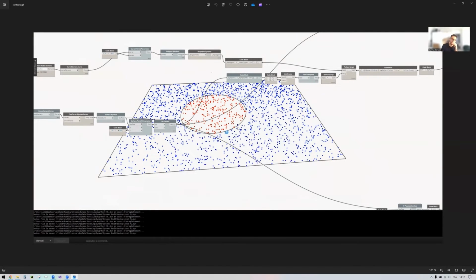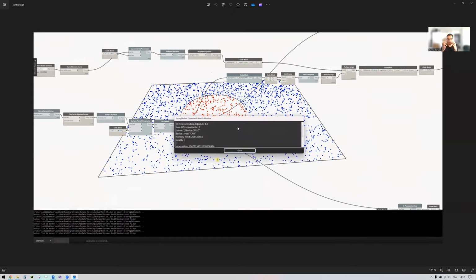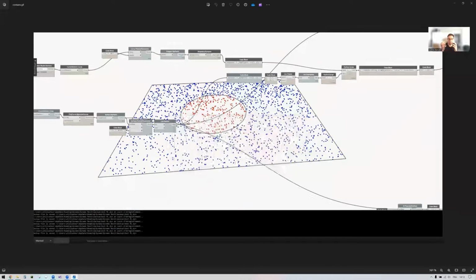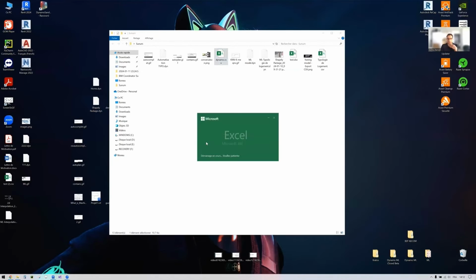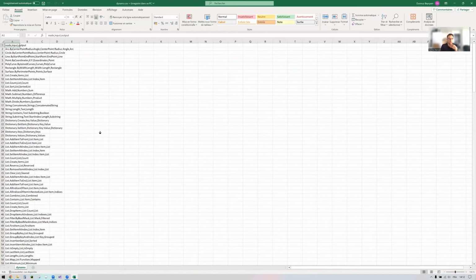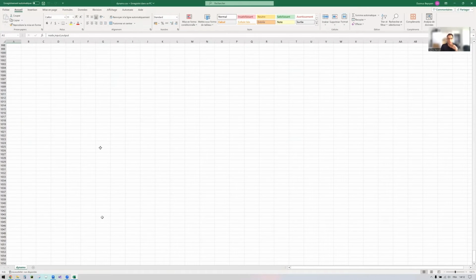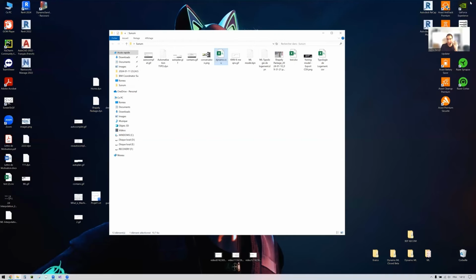What does this mean for us? This means that the model needs a lot of data for training. I showed you a Dynamo CSV earlier. I also told you that it had very little data. Remember, the more data you use to train a model, the better. And this number should be a minimum of 10,000, i.e. you feed 10,000 pieces of data into the ML model, which is your data set. Then the model starts to produce stable results.